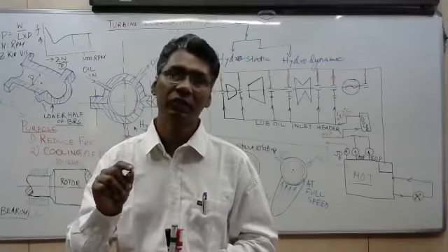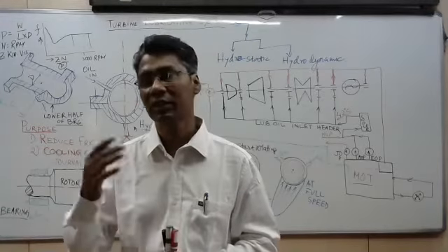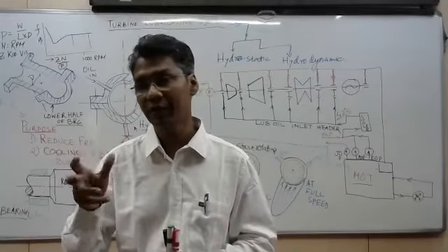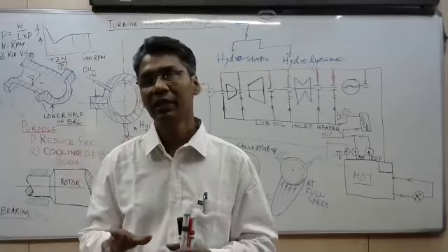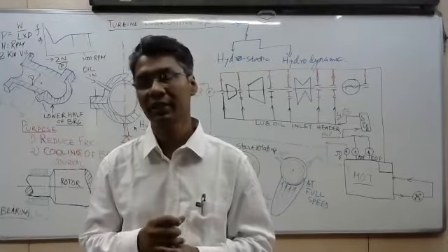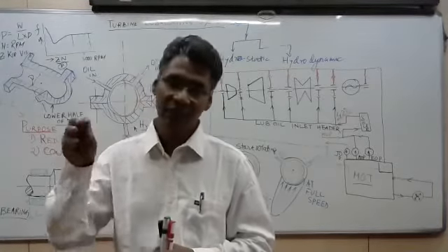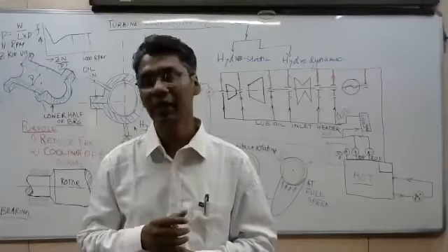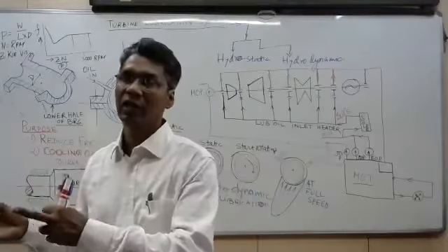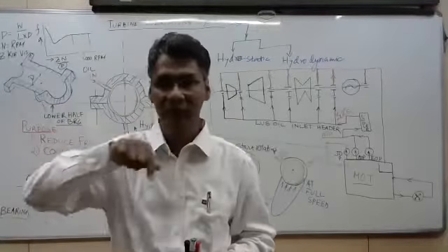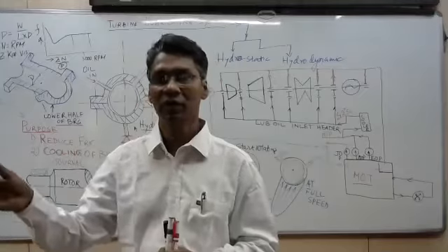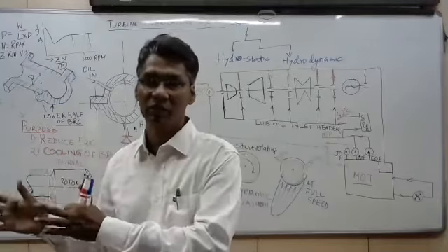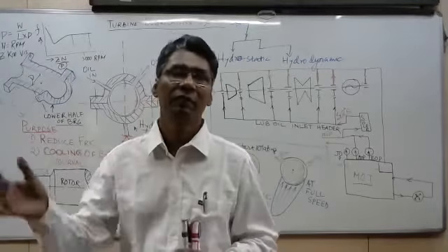And temperature, you know that viscosity changes with temperature. So that's why we have to maintain an oil inlet temperature. It is around 40 to 42 degrees centigrade. Oil is inserted into the bearing and hot oil is taken out. And hot oil is again circulated to the tank. Again it is cooled and purified in the centrifuge. So that is, in short, the bearing system.